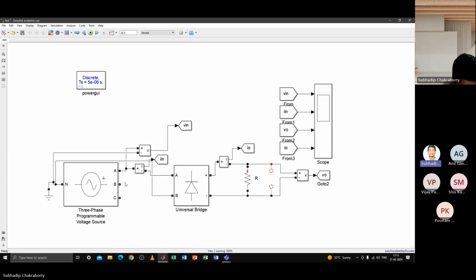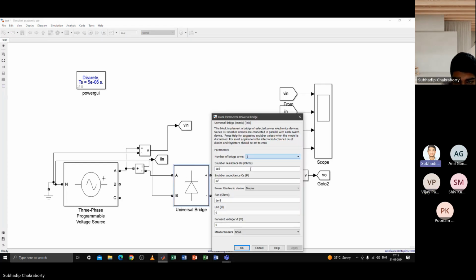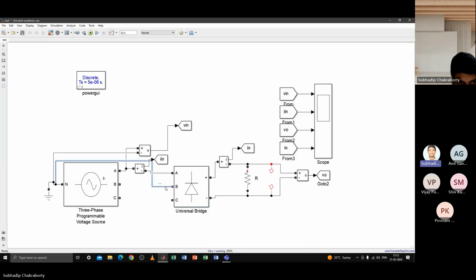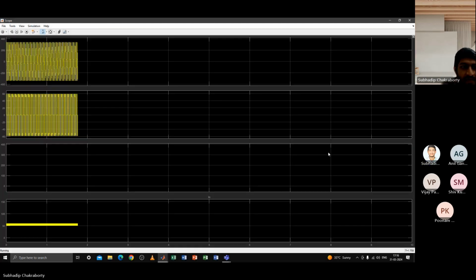Just see this example. Make it 3-leg and that is a 3-phase diode bridge rectifier. So now what do you have? You have a 3-phase diode bridge rectifier connected to R load, right? So what do you think? This load will be linear or non-linear, or power factor unity, non-unity? What comments can you give about it? We have solved many such problems. Linear as well as unity power factor. No, it will be non-linear. Just see, I will make you understand. Just let me simulate, okay? Your concept will be clear now.